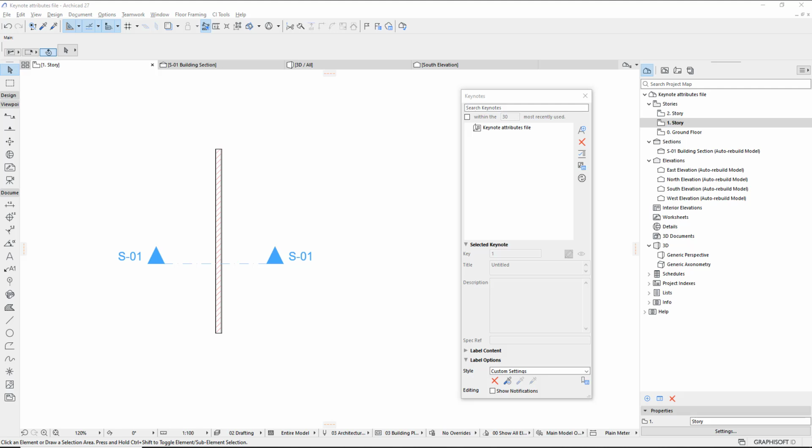Keynotes are a live database of notes in a centralized interface that can be imported and exported to and from projects and can be edited inside your ArchiCAD file as needed. It allows for notes to be linked to attributes in ArchiCAD for easy annotation of sections, elevations, and plan views, even down to detail level. Recently, the teamwork functionality was also introduced and can be used with team member permissions to restrict access to editing the notes on large projects.